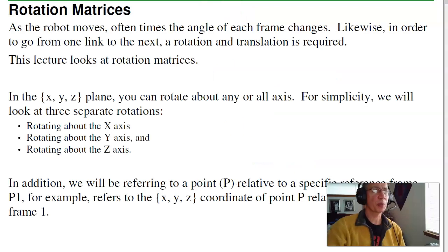Now in a robot, you've typically got joints powered by a motor, connected to other links. Like I want to go from the shoulder to the elbow to the wrist. As the joints move or rotate, the location of the subsequent reference frame, shoulder, elbow, wrist, depends upon the current reference frame and the angle. To figure out where these reference frames are, I need a rotation matrix, such as the reference frame on my elbow is going to rotate as I turn my shoulder around.